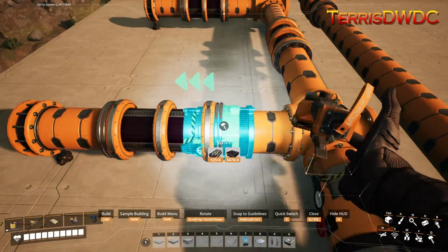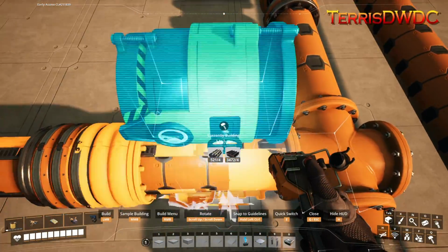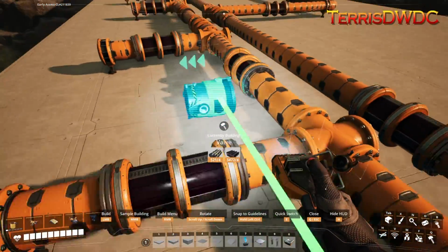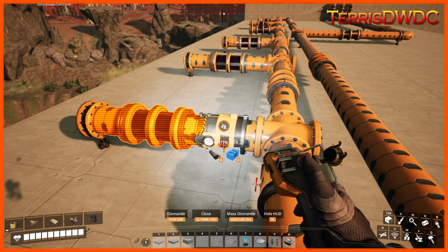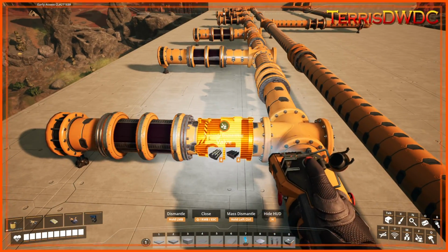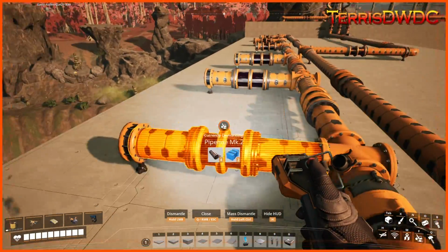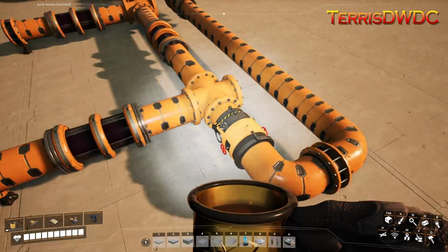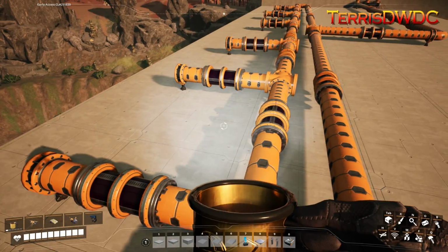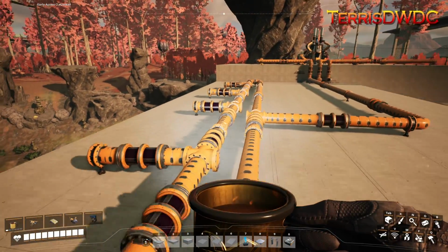Now, if you really wanted to be crazy about this, you could go through and put valves in on this as well too. But in most cases, where you're connecting to your pipe is going to be relatively close to the equipment that you're going to be using. So you're not really going to have room for a valve at each individual piece of equipment.